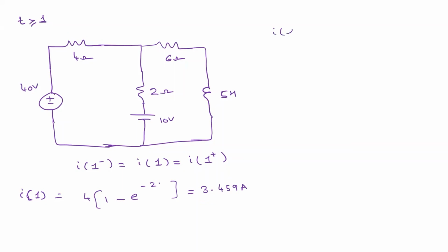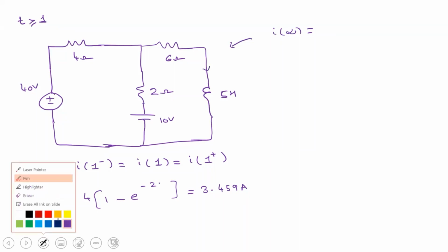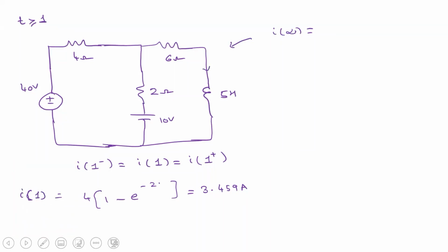So you need to calculate I infinite, right? So for this circuit, what is the value of I infinite? Inductor will be short circuit. So we can do KVL, sir. Yeah, I think we need to do that. So this is I infinite, right? So how to calculate this inductor current? This is short circuited, obviously, right? So now you need to calculate the inductor current at steady state. I think you need to apply KCL at this node, right? So that gives you the inductor current, I guess.